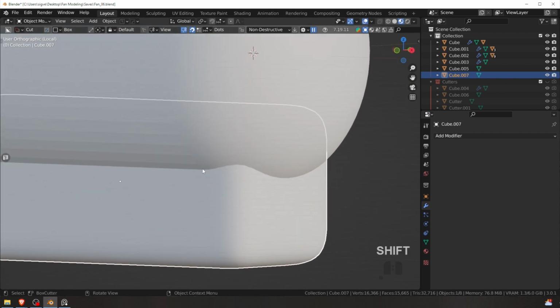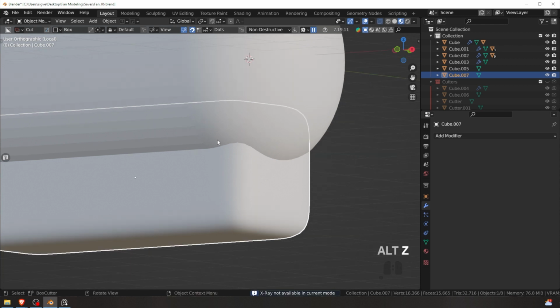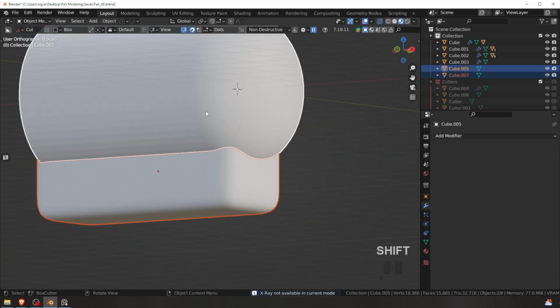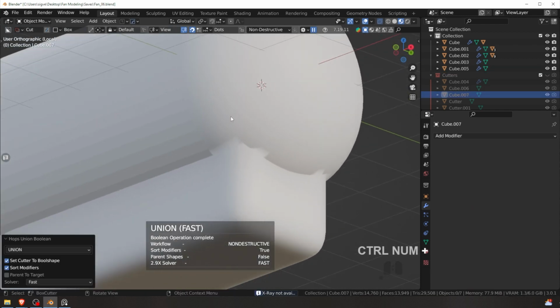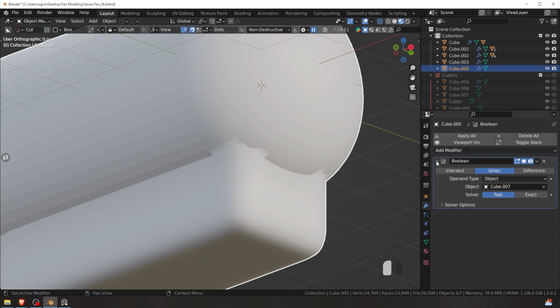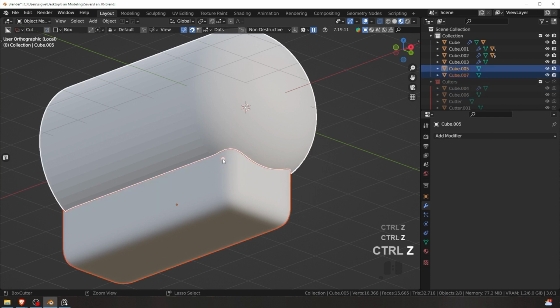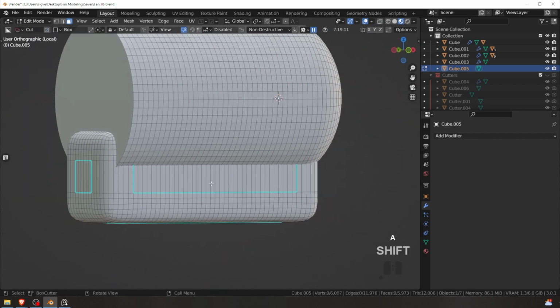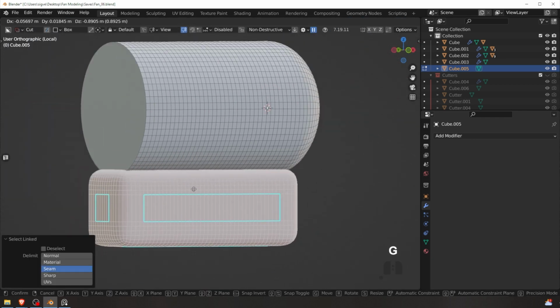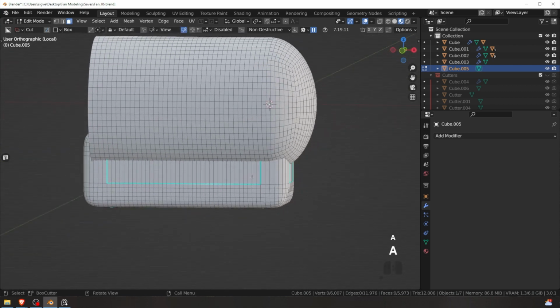By saying join, I mean joining the geometry itself by selecting them and pressing Ctrl plus J. I'm not talking about union. I'm just talking about joining them like this. Control and then Control J. That's it. Boom. Like that. Just two objects intersecting like that.